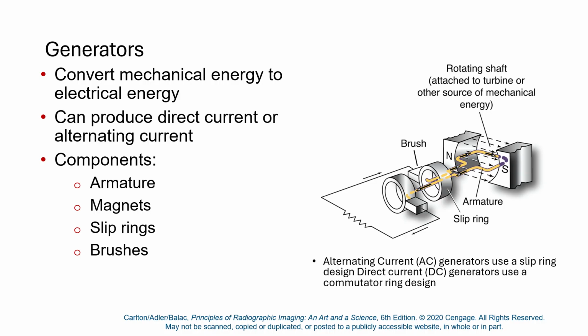Typically, a generator involves applying rotational motion to a wire coil inside a magnetic field, or alternatively, surrounding a bar magnet with coils of wire and spinning the bar magnet inside. Either one creates a changing magnetic field relative to the wire and so creates a current.